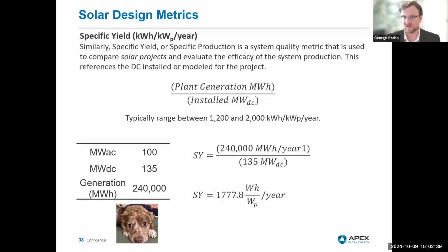And clipping is just a way to describe this: this was your maximum injection limit, you're producing this amount of power, and that delta, that's your clipped power. That can be captured in things like energy storage units, but often it's just lost.